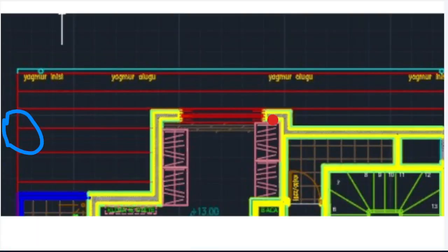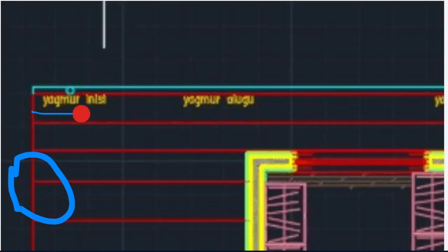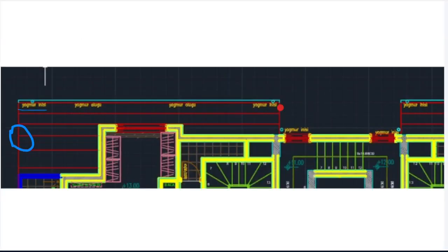And look at those information. Gutter. Gutter should not necessarily be at the corner. Maybe go 1 meter in and put one here, and one in the corner. Most of you are putting it like that. They are putting one at the center. That is why, in order to have 5 meter from both sides, you can cover 10 meter.